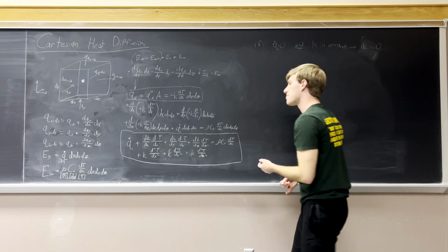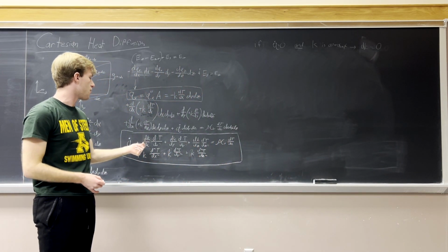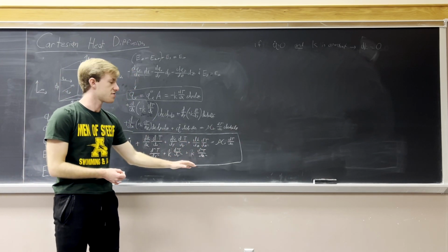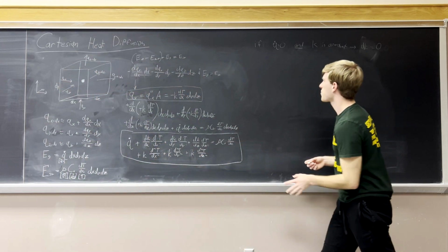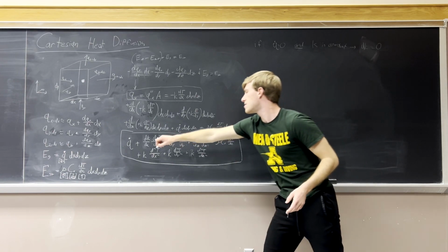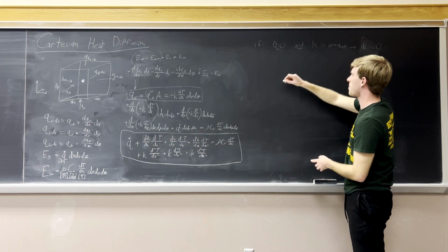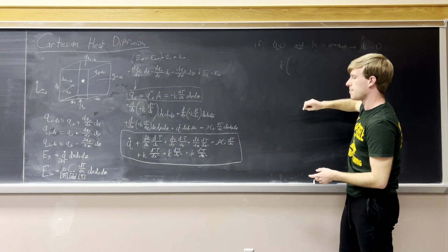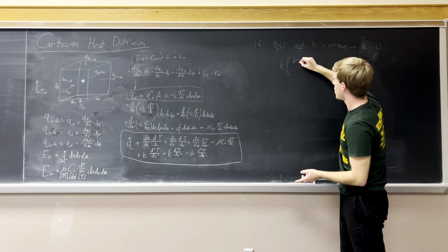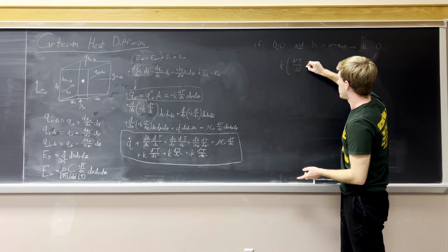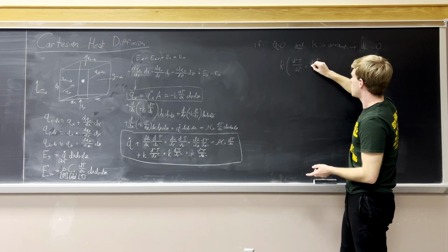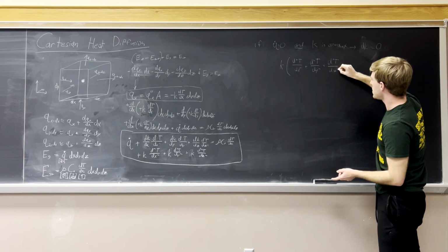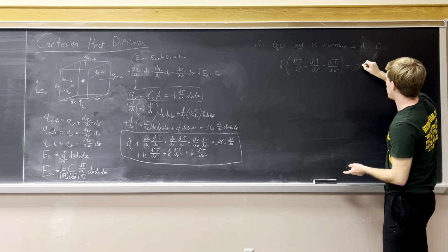So what does that mean? Well, the first term I wrote up here, dK over dx, is equal to 0. So this term becomes 0, this term becomes 0, this term becomes 0. So all we're left with is the bottom ones. And this, of course, is also 0. So factoring those in, this whole top row is equal to 0. We're left with K, and I'm going to factor it out because it's present for all of them, times d squared T over dx squared plus d squared T over dy squared plus d squared T over dz squared. And all of that is equal to rho c_v